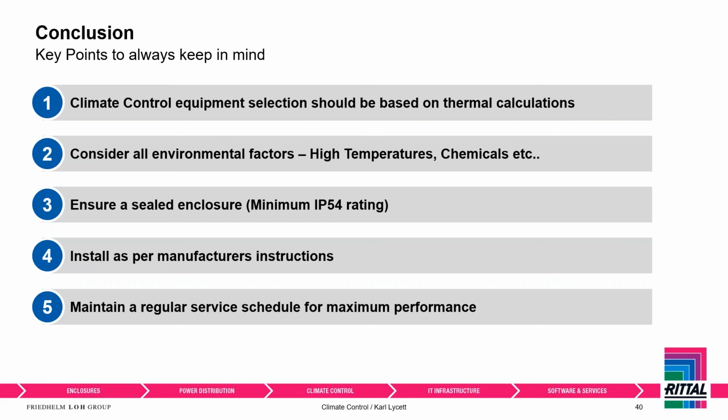Number three, make sure your enclosures are sealed. I've seen it before. People have put cooling units on the side, and then they've just put a bit of cotton wool over the massive holes where the fans and filters used to be. It's not going to cut it. The air's still going to get through cotton wool, I hate to tell you. You need to get those holes covered up and make sure it's a minimum of an IP54 rating for your enclosure.